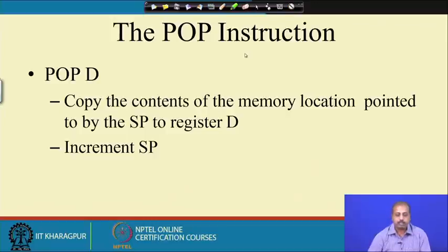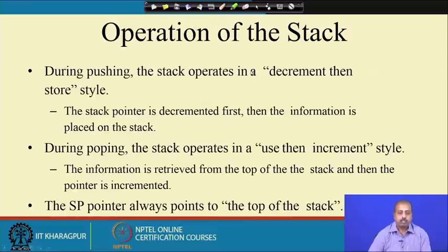Other than that, we have to understand the style in which these operations are done on the stack. During pushing, the stack operates in a decrement and then store style. First the stack pointer value is decremented, and then the value is stored onto the stack.